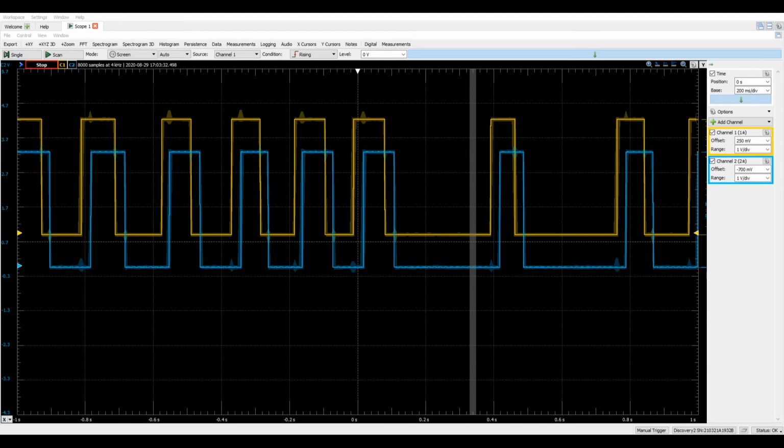But what I care about in this graph is actually the delay. I want to see whether it actually makes sense to delay. Let's see. Here's the yellow. At this point, for example, I will calculate how long it took. According to this, delta X is 22 milliseconds. That's actually according to spec. It's more than 20.